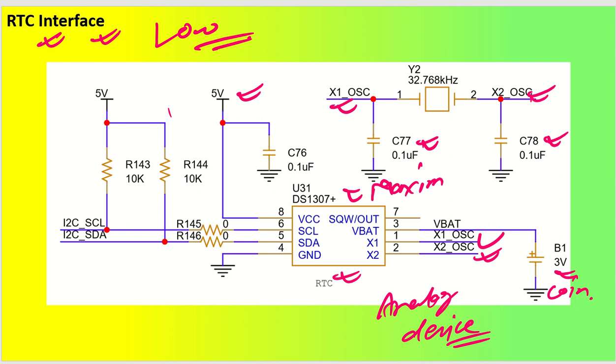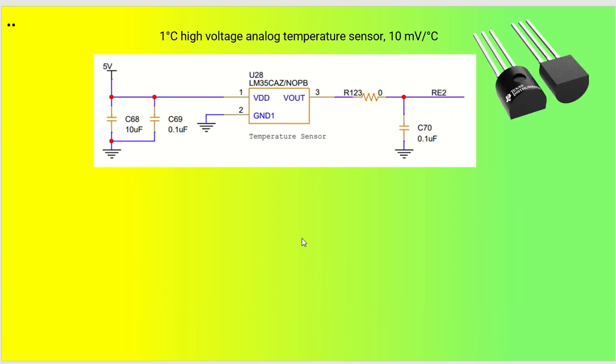Good. Next, we shall go ahead with a very robust application of a temperature sensor. I will tell you one more which is very useful. This is again a temperature sensor, which has a 10 millivolt per degree centigrade range. This is a TO92 package, and it is basically used in thermometer applications, automotive applications, and many other applications. It is very versatile and robust.